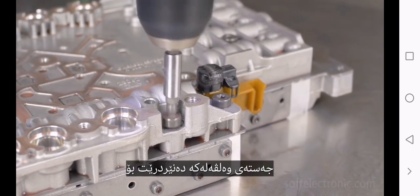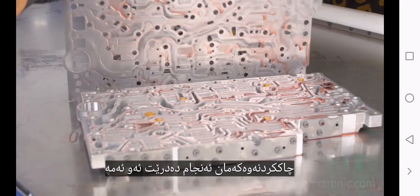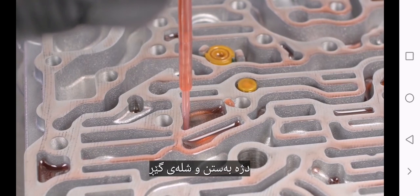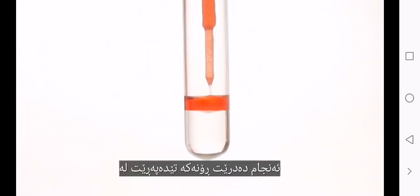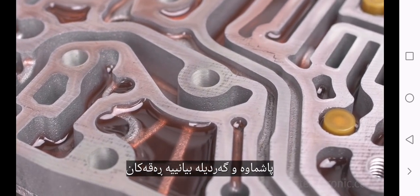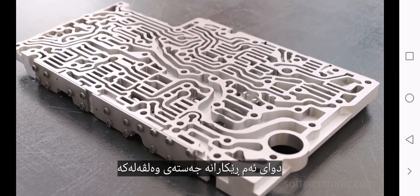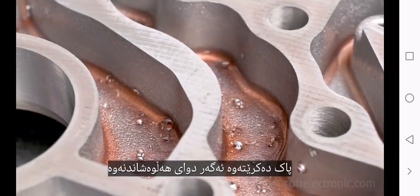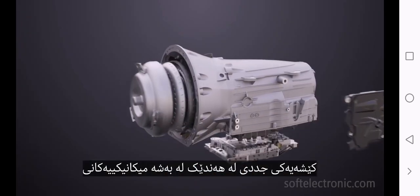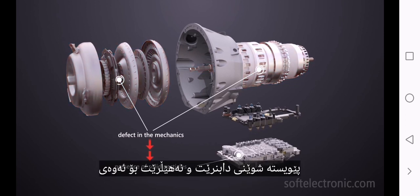The valve body is sent to the specialized department for maintenance, and if needed, a repair is carried out. It's disassembled into its composite elements, and after that, a test for the presence of antifreeze in the transmission fluid is performed. The oil passages in the plates are visually inspected for residue and solid foreign particles. After these procedures, the valve body is cleaned up. If after the dismantling there are residues and solid particles in the valve body, then there's a serious problem in some of the mechanical parts of the automatic transmission, and it needs to be located and eliminated.